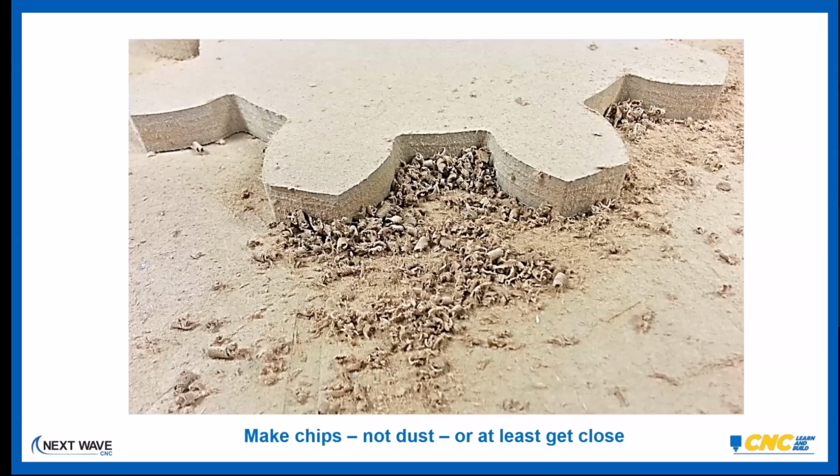But it is kind of surprising when you get your machine tuned in for much of your cutting and your chip load tuned in, you're not going to produce a lot of dust that goes floating around your shop. You're mostly going to get wood chips, maybe not this big, but you're going to get chips that aren't going to float around the shop. They're just going to either be easily vacuumed up or brushed up, which makes cleanup and using the machine a lot nicer.